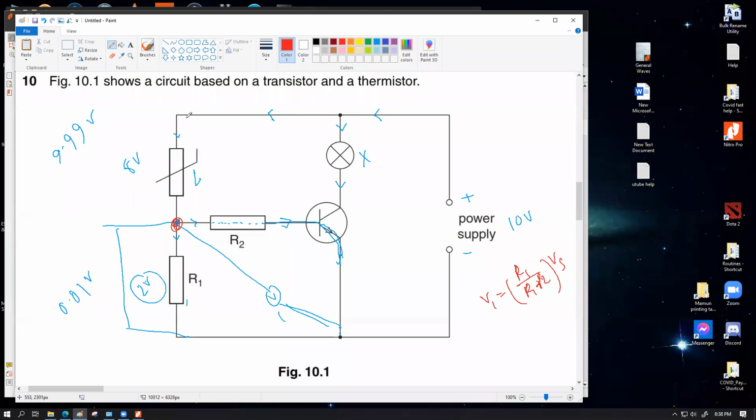I'm not using the current that is going to flow through this pathway to light up the bulb, but without having some current flowing through this part of the circuit, I cannot have this bulb automated, or have it work automatically with temperature variation. I'm trying to use this circuit to sense the temperature of the environment by introducing a thermistor. Because of the thermistor, this should be able to turn the light on and off for two different temperature ranges, let's say low temperature and high temperature, to achieve that variability of its performance.